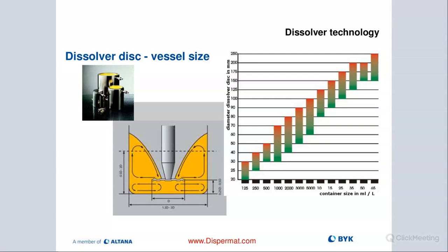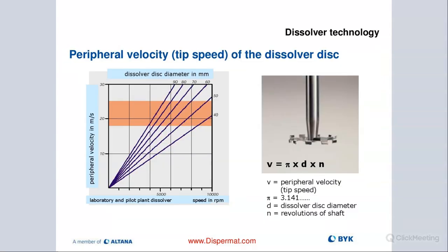And then depending on where you are with your viscosity, you can either move up or down with blade diameter. If your material is thinner, you want to reduce the diameter of your blade and basically make it smaller. That will give you better traction for low viscosity products. When you get really thick with your material, then you want to increase the blade diameter. And there'll be another slide.